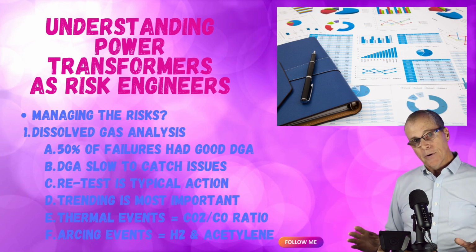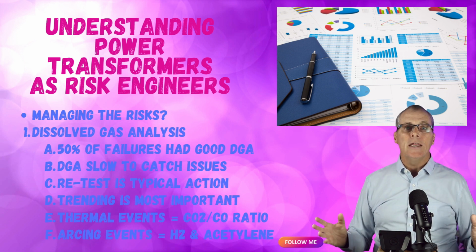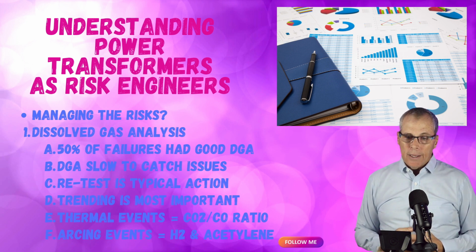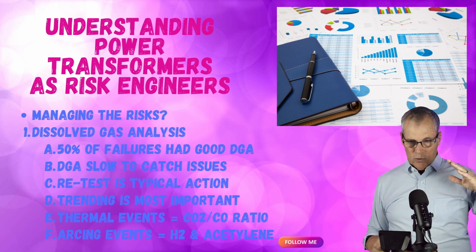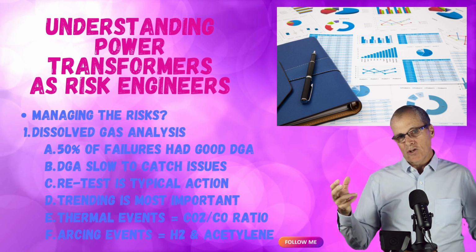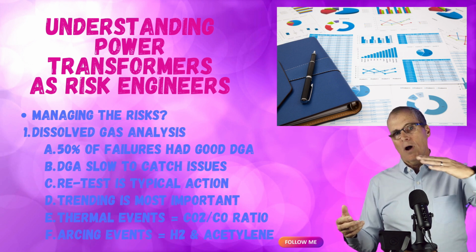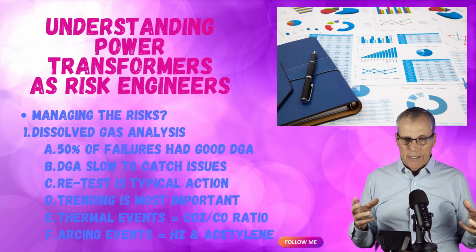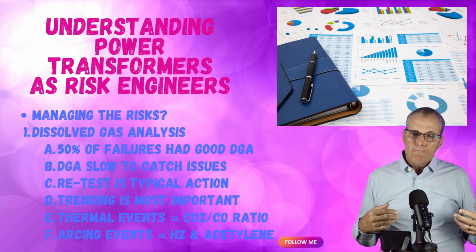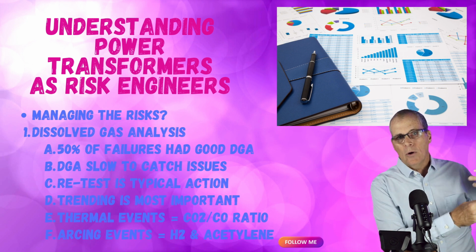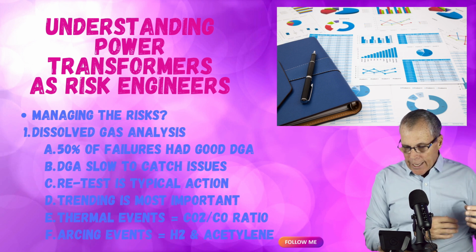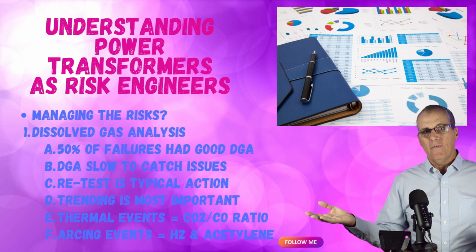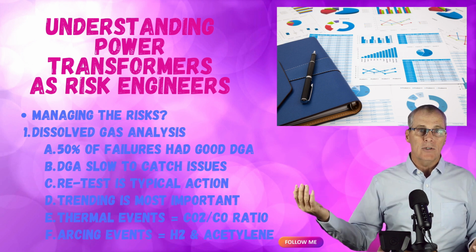What I've learned from my experience in understanding dissolved gas analysis reports is that you have to look at trends. And that's going to be the main thing that you'll see, especially when something is slow moving like this. You have to try and observe trends, and you're going to look for the trends in things that indicate overheating, and you'll learn that it's going to be the ratio of the CO2 and the CO, and you can kind of watch that ratio and figure out if, oh, well, maybe we have a fan that was replaced and they put it on backwards. And that's happened, folks.